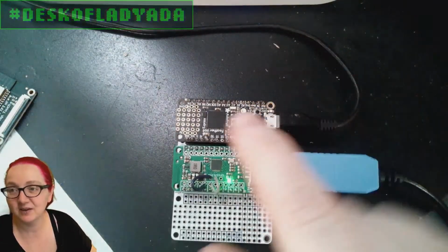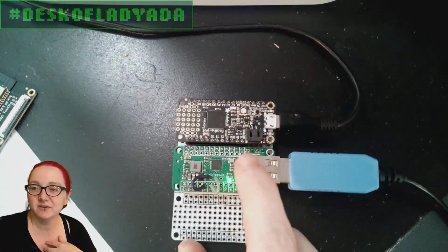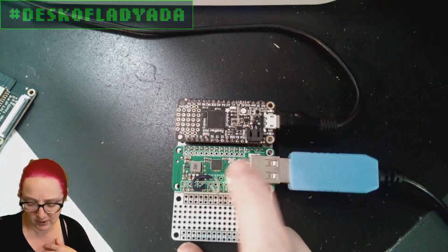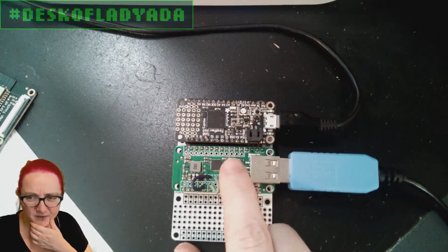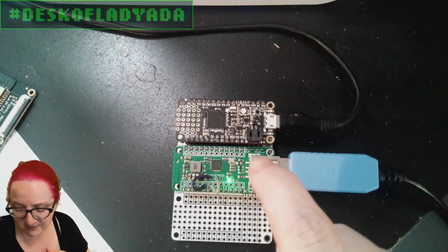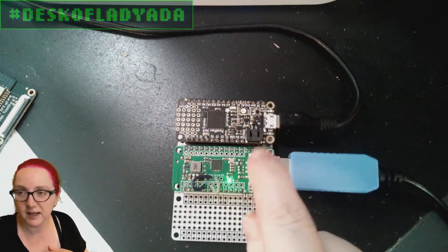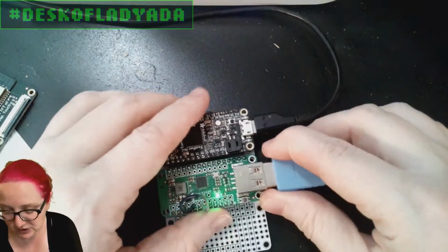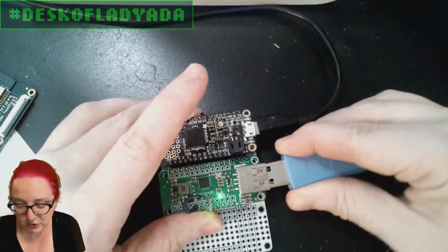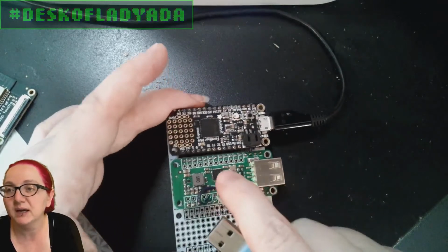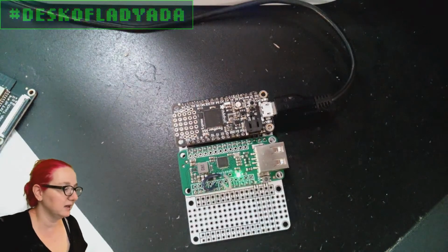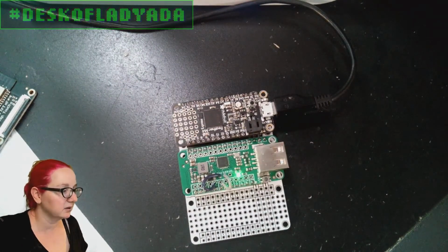So this is another piece of hardware I'm working on. This is the USB Host Featherwing. I don't know if I chatted about this on the show, I don't think I brought this onto Desk of Ladyada, but this allows implementing a USB host interface. It's a USB Type A connection. It works with any microcontroller, so it doesn't have to be an RP2040. It has a little boost converter, a USB Type A connection, and then if we go to the computer,